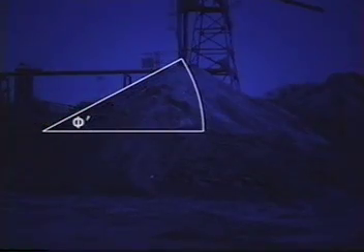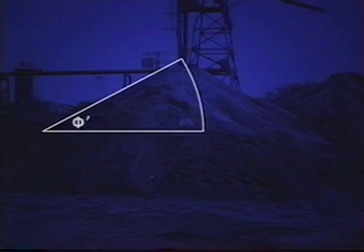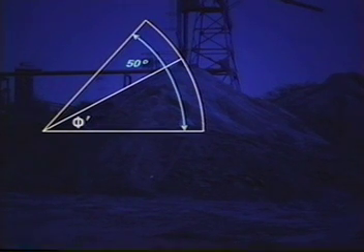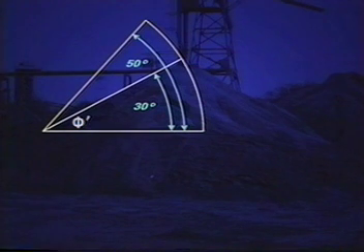The angle of the slope of a pile of soil, measured from the horizontal, is closely related to φ', the effective stress internal angle of shearing resistance. This is the basic parameter defining the shear strength of dry, cohesionless granular soils. The value of φ' will vary according to the particle sizes and density of the soil, but will typically be between 30 and 50 degrees. Clayey soils may have a φ value of less than 30 degrees.